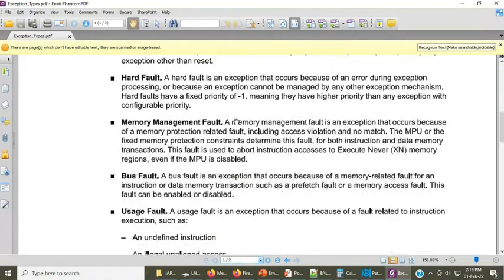Now coming to another error, the bus fault. What does that mean? Buses means the lines which take data from one device to another device. There are specific buses allotted to different memory regions or peripheral regions. Suddenly, if you change those buses and ask them to do something other than that, they will throw you an error which is called bus fault.